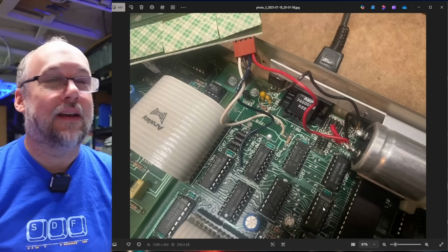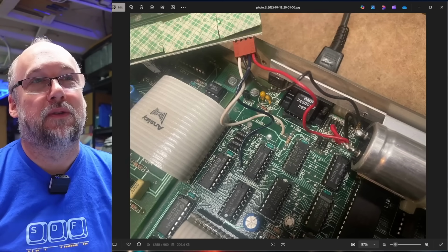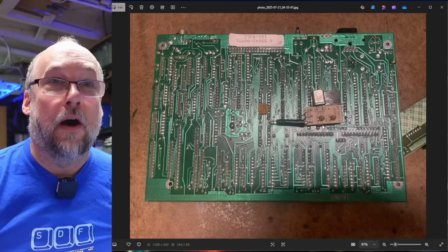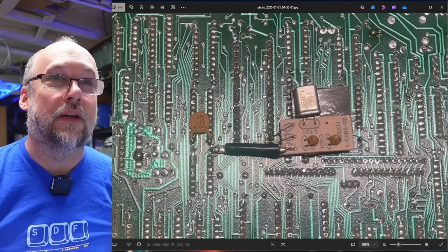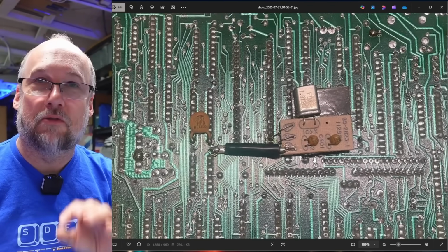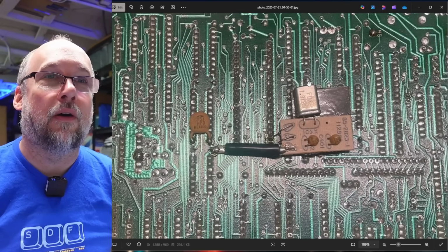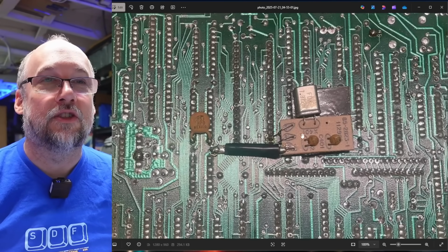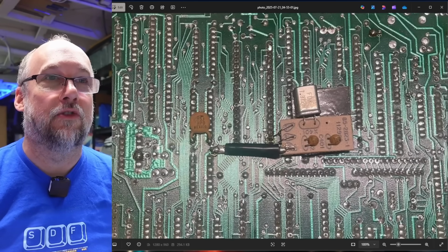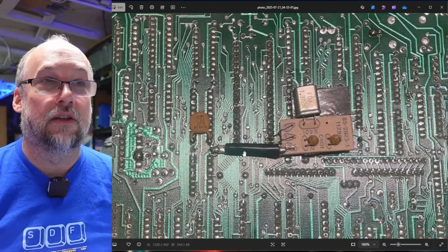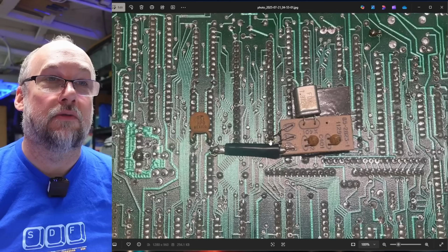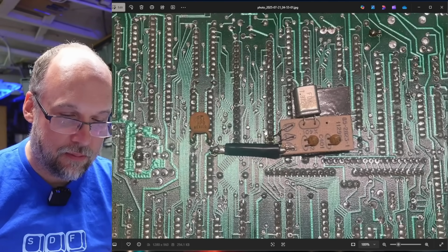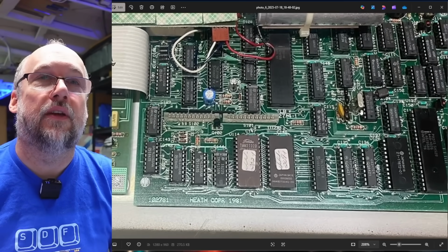Now, there is something else that's interesting that might preclude me from simply using something like this on this unit, and it's this. On the underside of the board, which Sark only noticed when he took the board out so he could repair the damaged trace, there's a small board with the crystal oscillator, 7.3728 megahertz, it looks like, connected to the microcontroller, the 8531. Looks like this is for ground, and that goes directly to here. So my assumption is they removed the crystal oscillator on the top side of the board. Well, actually, looking at the photograph, they didn't remove it.